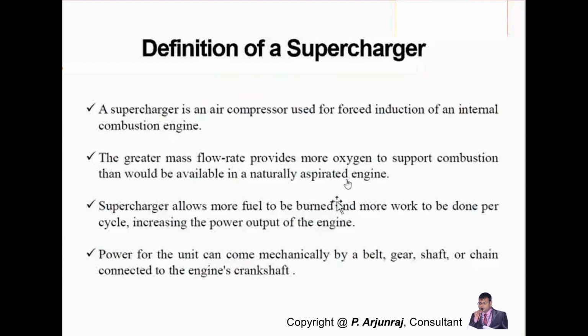And the supercharger, what is the advantage? It allows more fuel to be burned and more work, which we have also seen. Again, I told you this is not going to happen in just one cycle. This should be throughout the cycle, as long as the engine is on. When the engine is off, nobody is going to worry about that. And the main objective is to increase the power output of it. This is the key word.